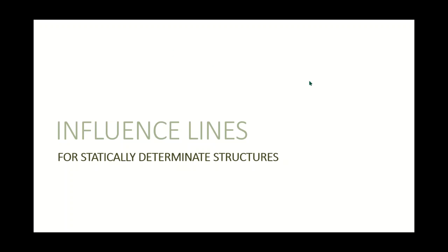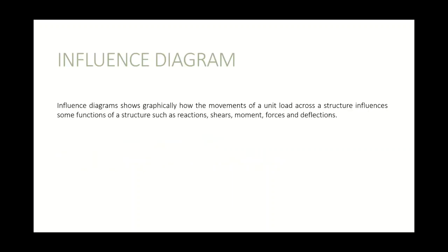Okay, so this lecture video will be about influence lines for statically determinate structures. Now, by definition, an influence diagram shows graphically how the movement of a unit load across a structure influences some functions of a structure such as reactions, shear, moment, forces, and deflections.